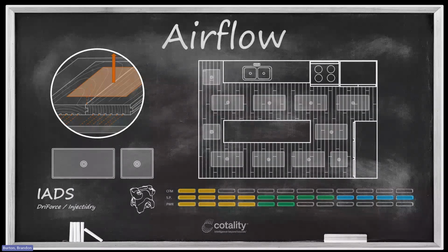To understand that, I'm going to put these mats now on the hardwood floor. Notice my placement and how my placement is very intentional and very strategic. The first thing I want you to understand about the placement is that my mats are perpendicular to the planks. Now think about the reason why for just a moment.